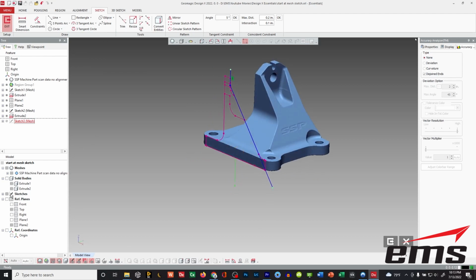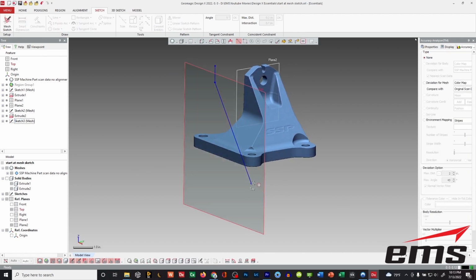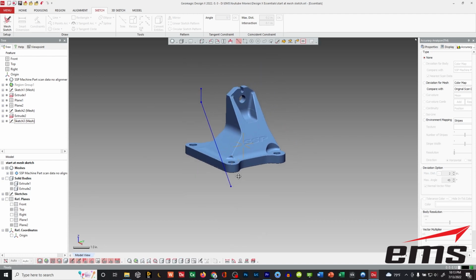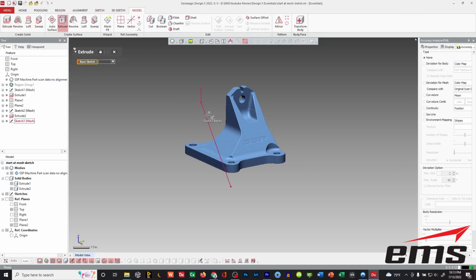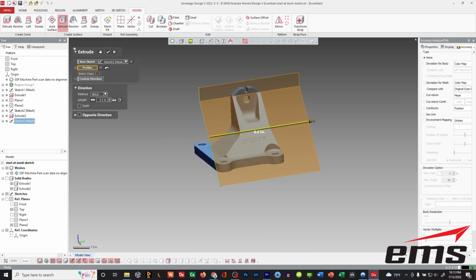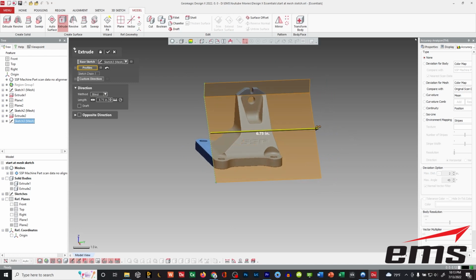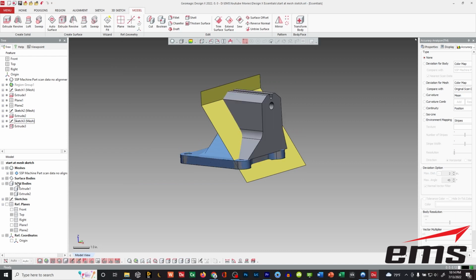Okay. And I'll leave the solids off for a minute and let's exit out. Okay. And yes, we had the disjoint ends turned on, but I don't care because I'm going to be doing a surface and it's not a requirement. So back to model. And instead of doing extrude here, I'm going to do an extrude here as a surface. Okay. So that doesn't have to be closed up. And this is just a surface skin. Okay. And I just got to make sure I go far enough. Let's go about right there. Okay. Surfaces are yellow, solids are gray by default.